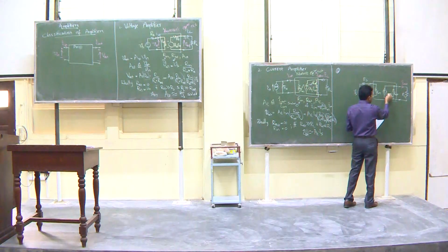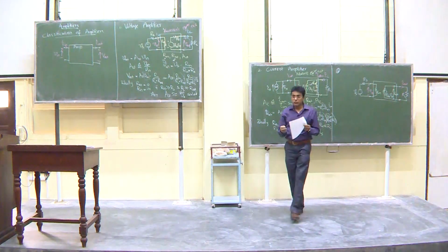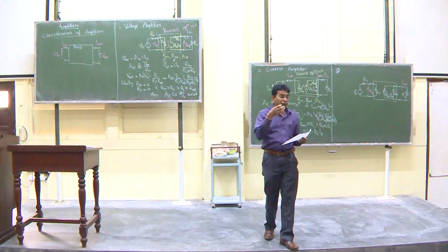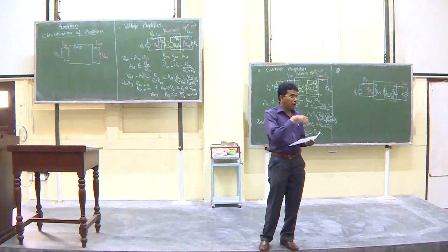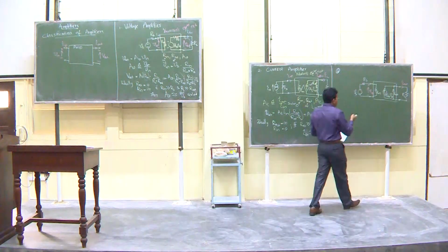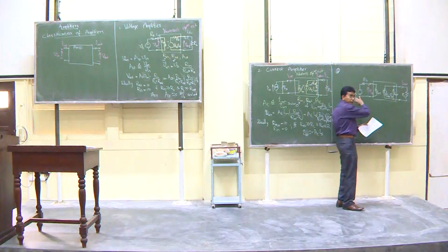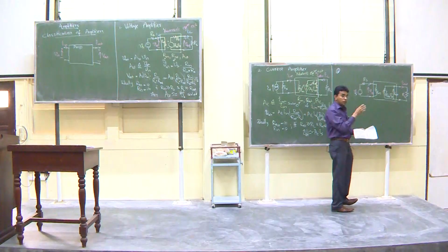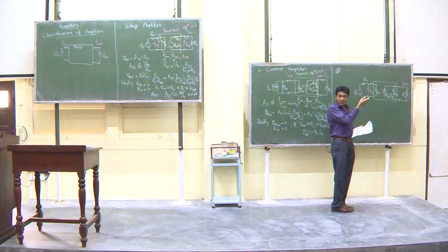So that is the conductance GM. We call this GM because it has the units of conductance, 1 over resistance, 1 over ohms, or Siemens. So this is called transconductance gain. Trans is between. So what we are going to do is convert a voltage into a current, so you are going to multiply by a conductance, right?